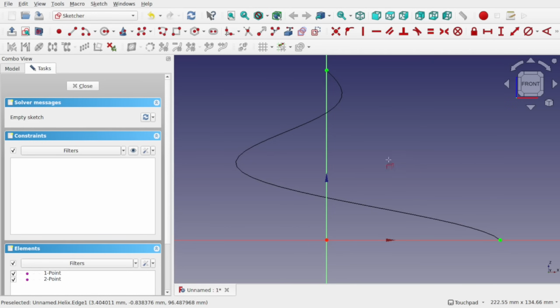Next thing I'm going to do is create a line. So this is going to be the edge of this helix and creates the edge of the blade. The thing I don't want to do is connect up to this point. I want to keep it in alignment with this point because this point will move out here, and that's done by altering the angle of this helix. So if I sketch a line by the left hand side of this, and come down, and then go past this center point and connect up to the vertical axis.